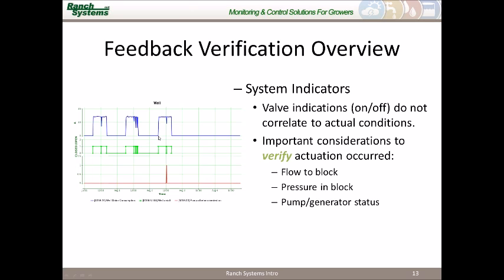But what we've also done is we say that if the water level is low, that there's a demand for the system, and if the valve is turned on and there's no amperage coming from the system or no flow, we use this as a way to indicate here with this new sensor down below, which is the pump off when needed on sensor that's been configured manually.